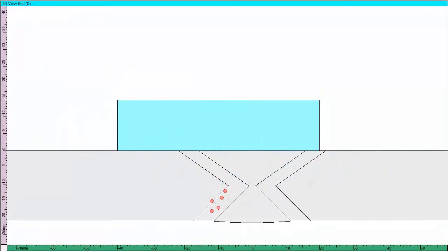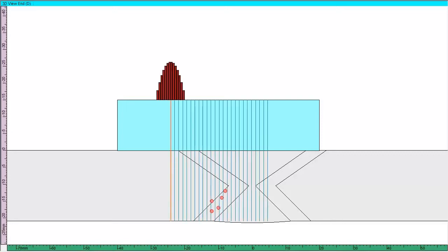For examination of base material, or if the weld crown is ground flush, a 1D linear array probe in direct contact or fixed on a 0-degree L-wave wedge can provide good coverage using electronic linear scanning with a partial aperture of the probe. This animation illustrates the probe configuration and the coverage of the straight beam examination. For this case, 10 MHz probes will typically be used. Comparison of the responses from the shear wave beams and the L-wave beams can help to discriminate between HTHA damage and inclusions in the base material.